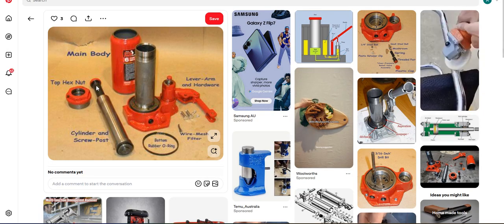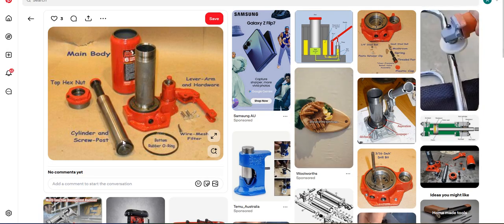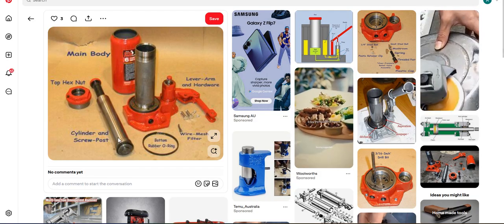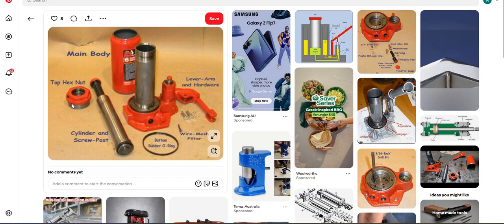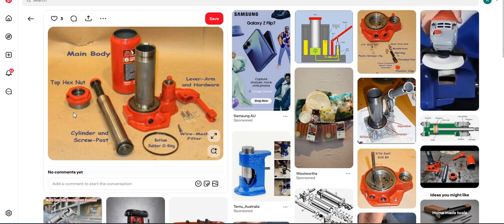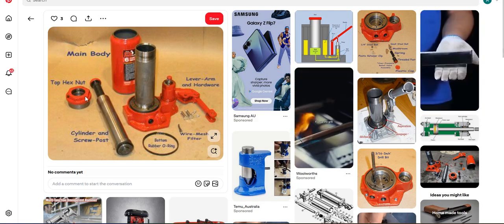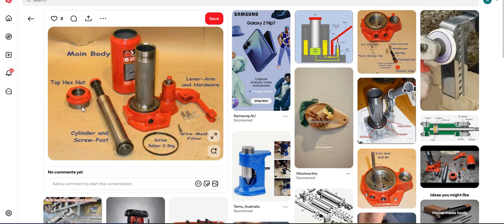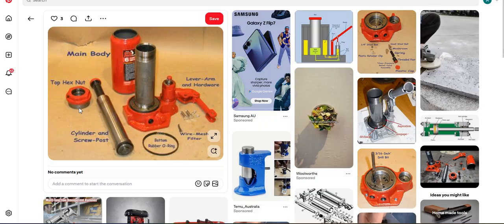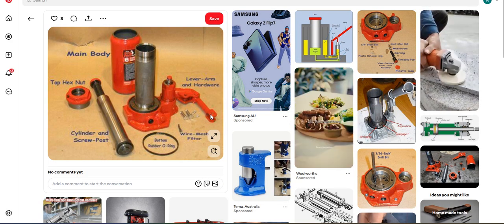So you can see that we're going to have the internal and the external parts. Both are going to be done by the machining process. They're going to be joined together. This nut is going to be done by the casting, then machining. The sand casting, because it's made of cast iron, and that is going to be machined on the turning machine.